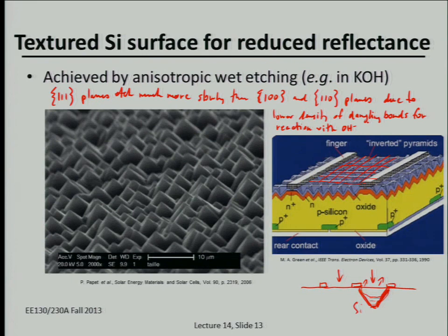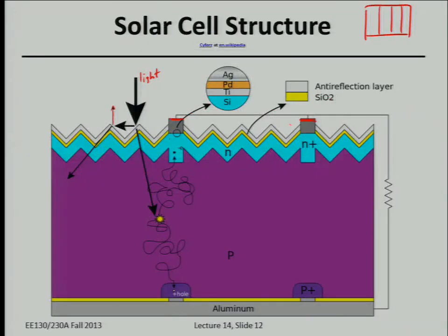Okay. All right. So then, if you etch with time, over time, then you end up with... Oh, okay. So then the key here is that each of these sidewall surfaces is a 111 surface, right? Because those are etching more slowly. The silicon is etching faster, like vertically, in the 100 direction. So on this slide here, I should have pointed out that this plane, this direction sticking out, is a 111 direction.